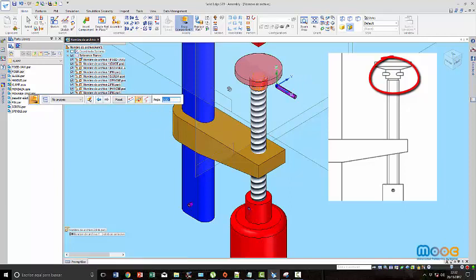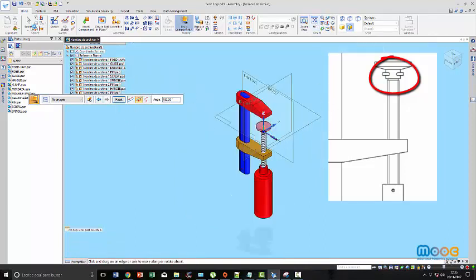I want to see the pin just on the front view. So I rotate 180 degrees and I will have the fixer in the position I want for my draft, and also the pin. I position first the pin, then I delete the relationship and I can rotate the fixer.